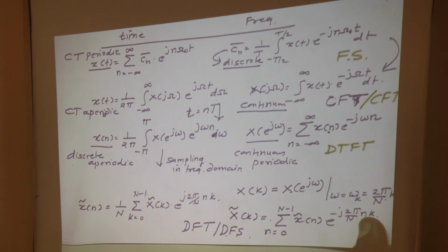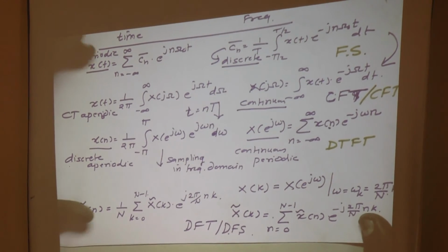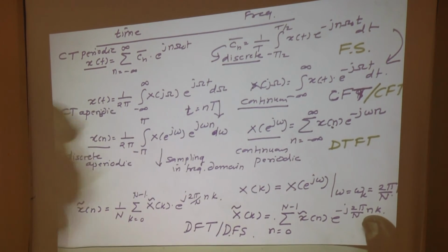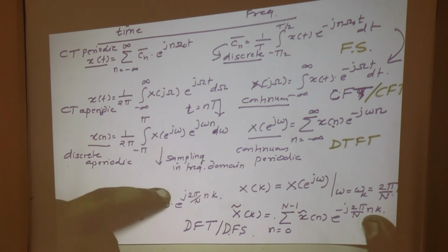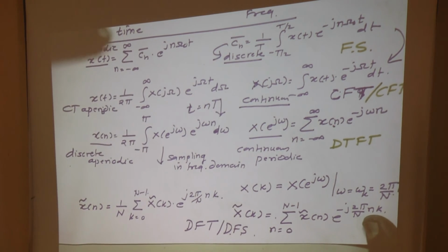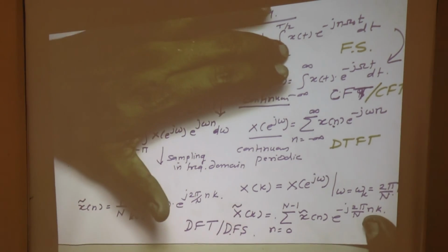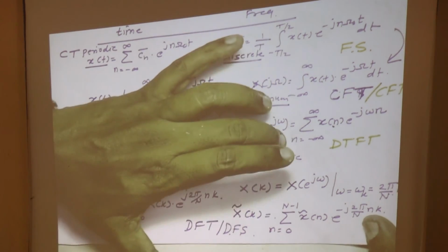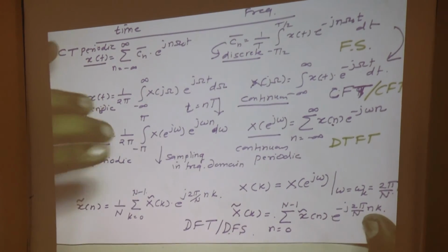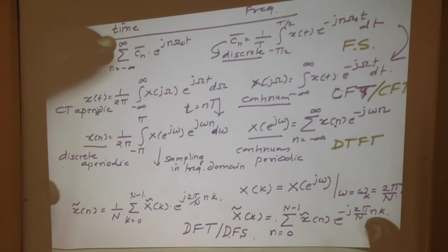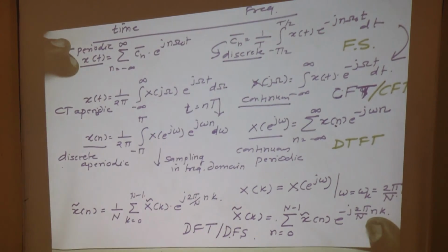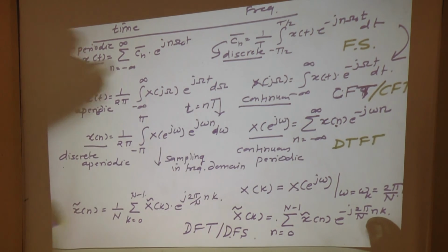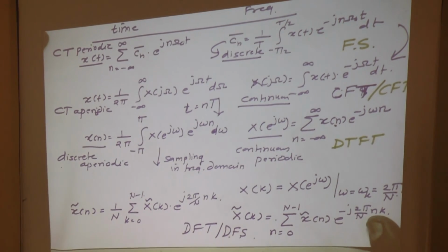So I rewrite, this is in perspective all the Fourier transforms, but as I have said in the first class, you don't require to remember all these equations. Only remember that periodic in one domain is discrete in the other domain. If it is periodic and discrete here, it will be periodic and discrete there, because periodicity in one domain is associated with discreteness in the other domain. So in both the domains the sequences are periodic and discrete.